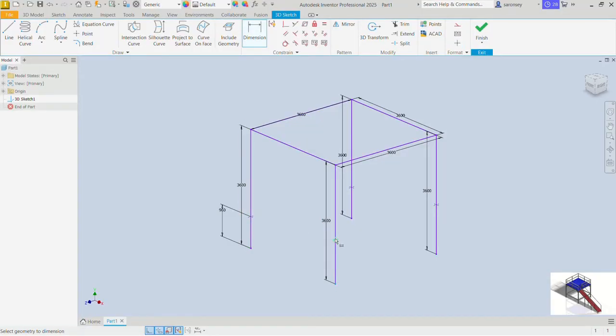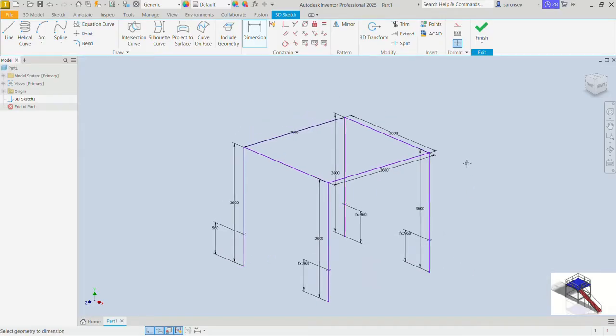Also between this point and this very one, you don't have to even type, you just select the 960. It would replicate that here and you can check. Also between this point and that, we'll select the 960 and check. In that case, in the future when we change this length, it would affect all these. Let's do the last one also between those 2 points is 960. Let's check. Now let's pick the line command again and connect all the points. You can right click and OK.